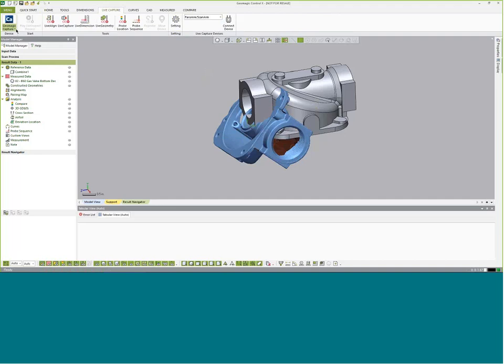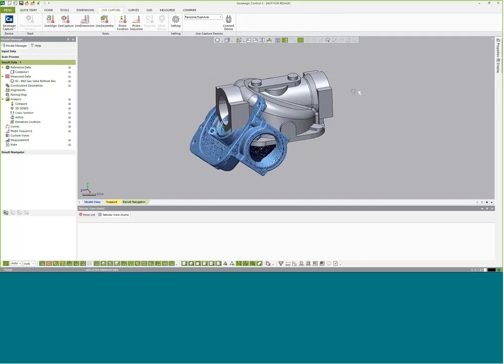Settings are right up front, and then we have structured light devices broken out over here. So let's talk about some of our live tools here. These are a lot of things that are very different from Control. Live Align is just that. It's to align your portable CMM with your CAD model. You just basically click it, and then we can select whatever it is we want to probe on our CAD model and align our hardware device to our global coordinate system with our CAD model.